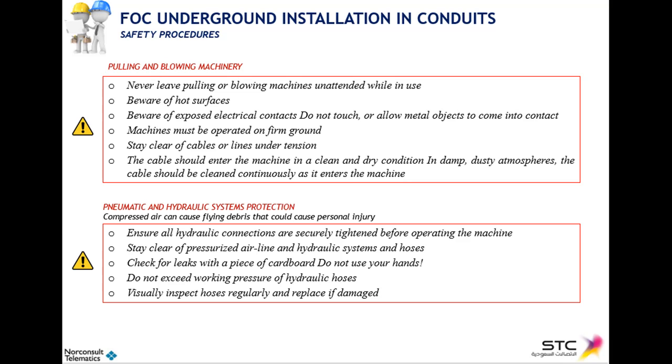Otherwise, when you fire up the equipment, those can explode and hit you, causing some damage to you guys. So this is about making sure that all connections and hoses in pneumatic and hydraulic systems can operate and are properly connected before you start working with equipment.